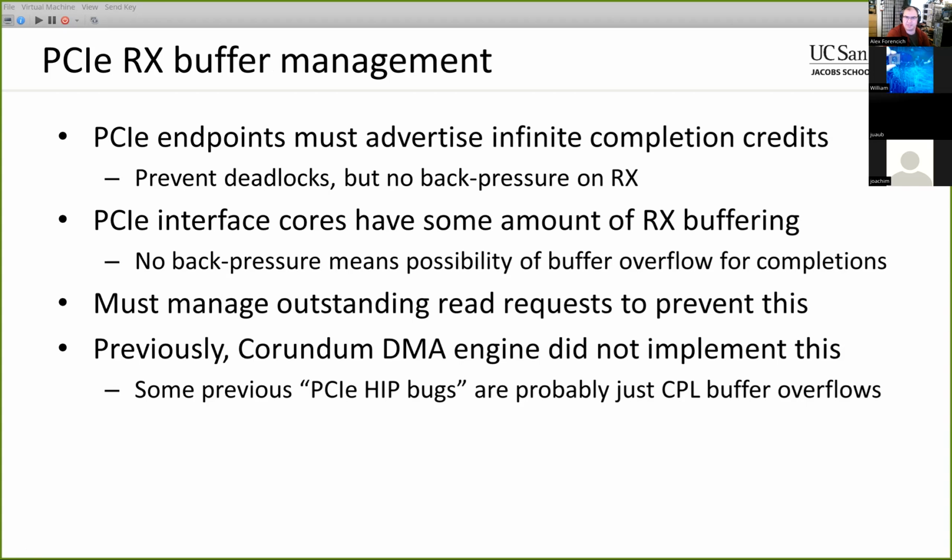Basically, PCI Express endpoints must advertise infinite completion credits, and this is to prevent deadlocks. If you advertise infinite completion credits, then all of the traffic can drain out, and you're not going to end up in a deadlock situation in a PCI Express system. So that's a rather important aspect.